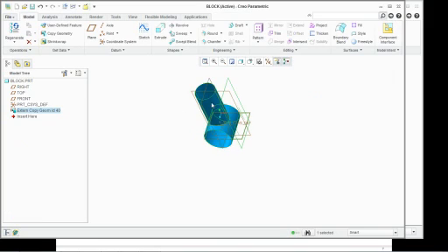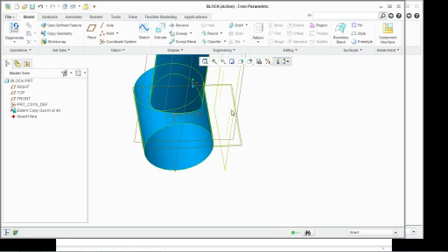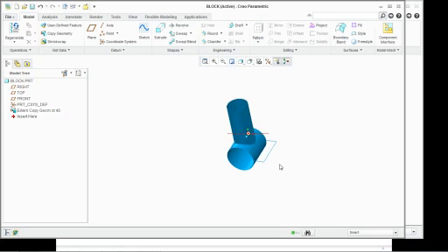So I do that, notice it comes in. It does turn it blue. This is copied geometry. It's not actually a skeleton, it's just copied geometry. So I'm going to come in and create two holes and a fin from this in just a moment, which actually I could go ahead and do that from here, but I want to make sure I get all of my references properly.